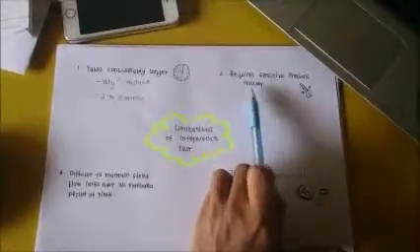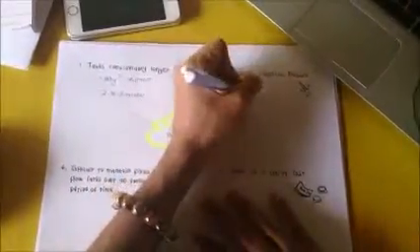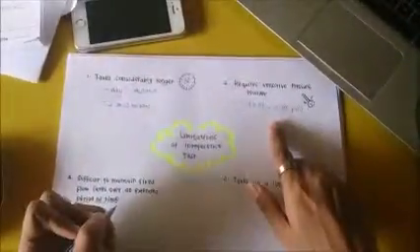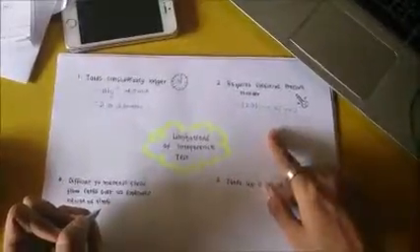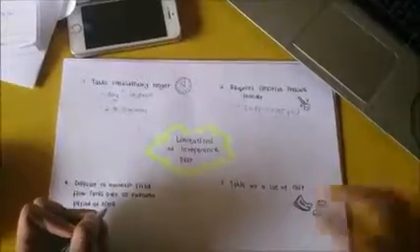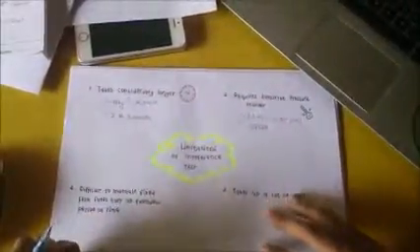And secondly, you require a very sensitive pressure recorder, because the pressure transient that might be observed in the observation well can be as small as 0.01 to 0.05 psi. As you can see, this is a very small pressure. So for this, you might need a very accurate pressure recorder, or else you might miss this and assume that there is no communication. An example of a sensitive pressure recorder would be the SPIDR pressure recorder, which is now used a lot in the industry.